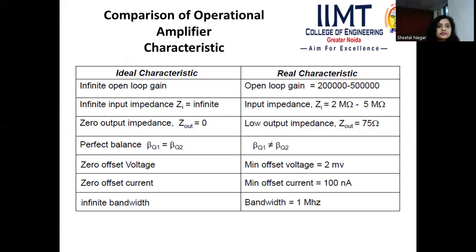Ideally, we discussed all the characteristics: infinite open loop gain, infinite input impedance, zero output impedance, perfect balance, zero offset voltage, zero offset current, and infinite bandwidth.